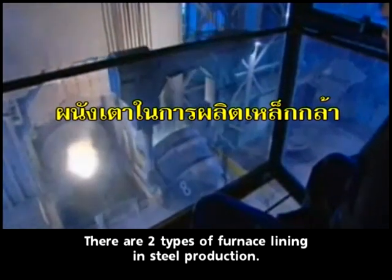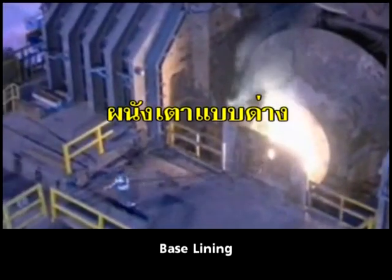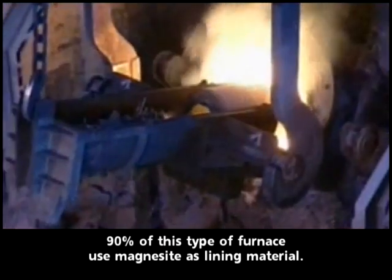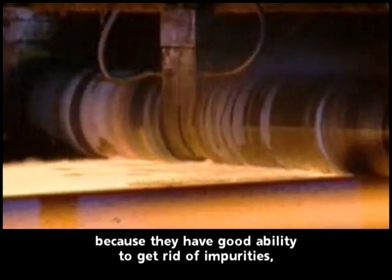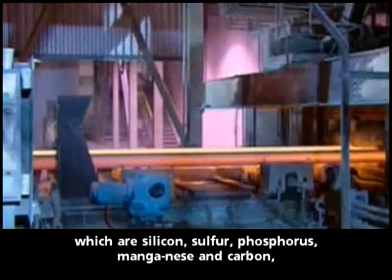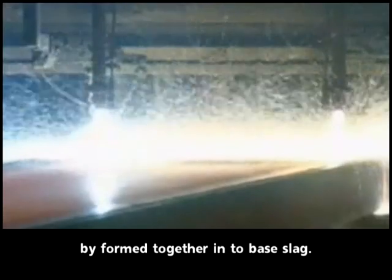There are two types of furnace lining in steel production. 1. Base lining. 2. Acid lining. Base lining. 90% of this type of furnace uses magnesite as lining material. The lining is arranged to form fire brick. The flux used is a base substance because it has good ability to get rid of impurities, which are silicon, sulfur, phosphorus, manganese and carbon, by forming them together into base slag.